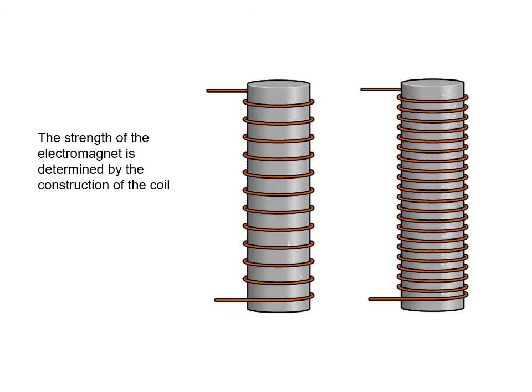And again, the third thing that affects my magnetism, or my electromagnet, is my current. As I apply more current, I line up more magnetic domains. Lining up more domains means that I've created more flux. I can keep applying current until I reach the point of saturation. And again, saturation is a point where adding more current or magnetizing force does not increase the magnetic potential, because my system has already reached its maximum.